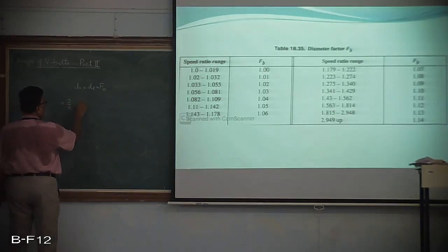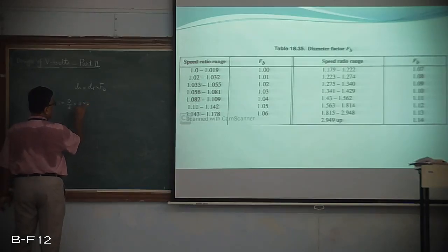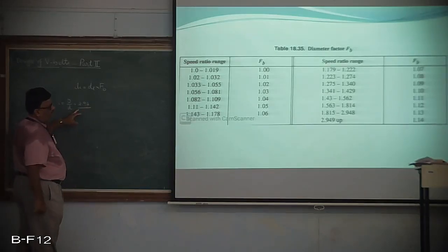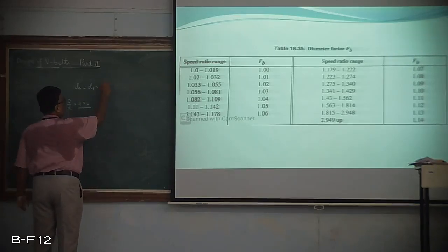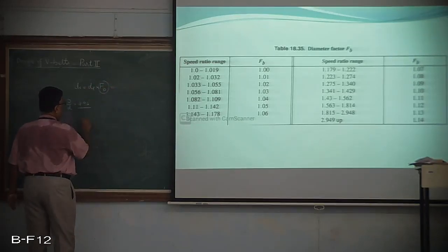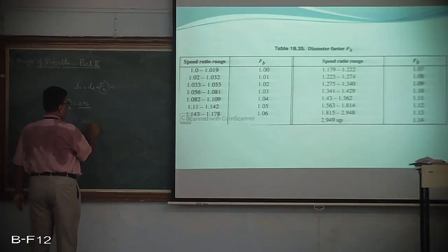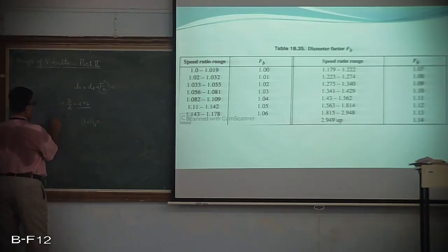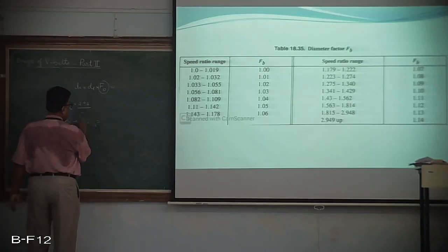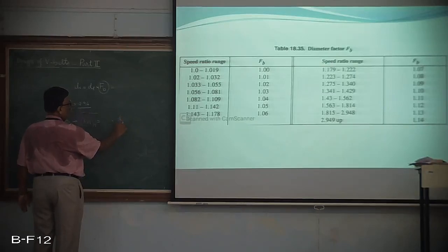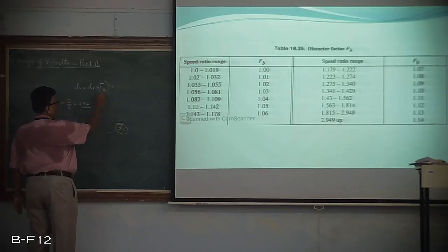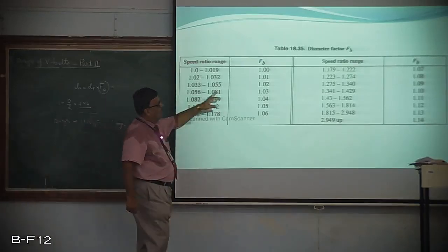That is 2.94 or something like that. Yesterday we had got it. So if you look at this, for this particular velocity ratio, this FB needs to be calculated, because once we know this, we have the kilowatt rating for each belt. For example, if you go for D type, it is given in the table like this. I have already shown you whatever is there. Then you have to use this DE in the denominator here, and this has to be calculated with the help of FB.